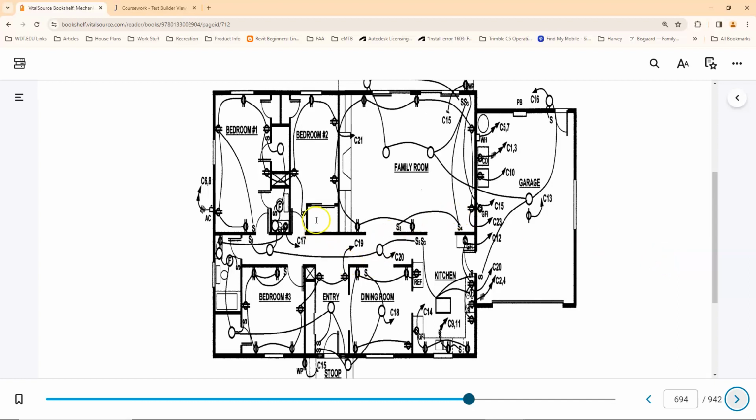So this configuration is showing how that circuit arrangement might look on a plan. And you can see that this one is actually tying the electrical into the lighting circuits, right? So in this scenario, let's just look at bedroom number 1 up here. You can see that the panel is fed from circuit 6 and 8 going into this exterior outlet. And it looks like it's tied into this one adjacent to it, but it is not. If we follow this bedroom 1 circuit all the way back, you can see that it terminates at this outlet. I'm not sure why they jumped across from this one over to the switch. I think I would have just fed it right off of this one, but regardless, let's follow the circuit back.